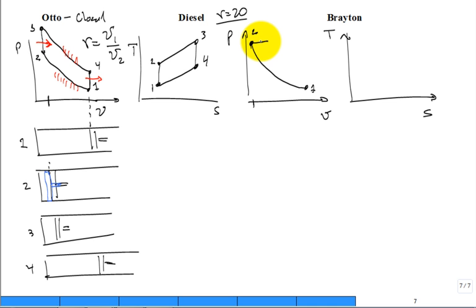But anyway, fuel injectors are the way you mix the air and the fuel, and you spray it in typically at the intake manifold. It's atmospheric pressure. It's easy done. Then you're compressing in that compression stroke in a gasoline engine. It's the air-fuel mixture that's being compressed. Now, what about a diesel? You have a fuel injector, but you don't inject the fuel in the air mix before it gets ingested into the cylinder, do you? What's drawn into the cylinder is just pure air. Then it goes into the compression stroke. There's no fuel mix. When does the fuel show up? When the fuel injector sprays it into that high pressure, high temperature combustion chamber.